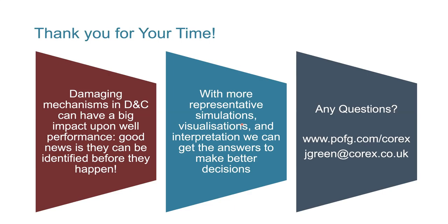Then Hussein has asked, is the density of the mud affecting the test? 100%. What one should be trying to reflect in a laboratory simulation is the well conditions. In the well, the higher the density of the mud, the higher the overbalance pressure will be, and the higher the potential losses, or the nature of the mud cake might change. So in laboratory simulations and visualizations, we should be reflecting that. If there's a higher density mud, we should reflect that same overbalance pressure in the lab.